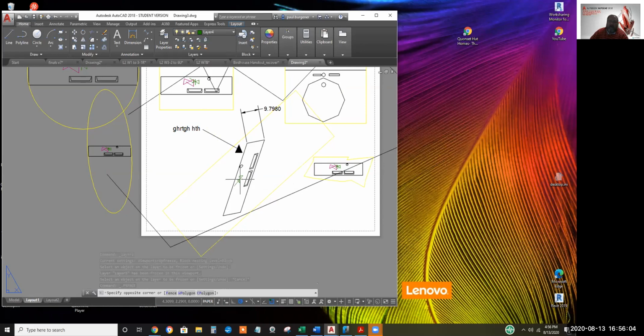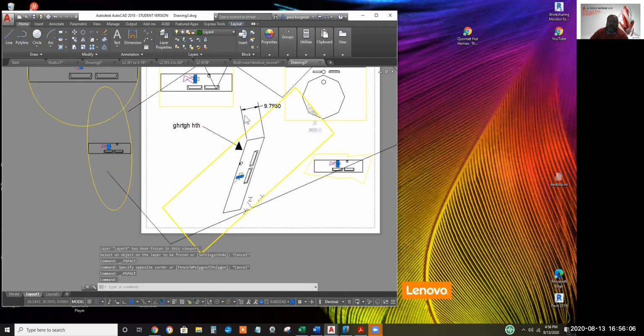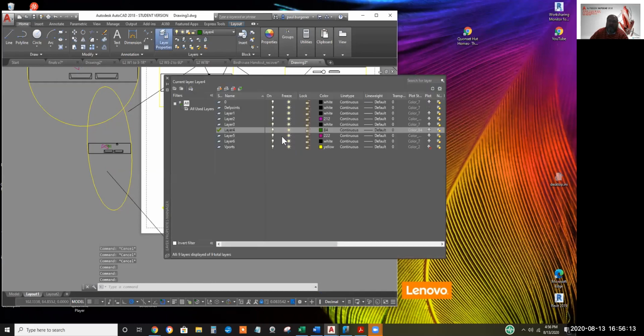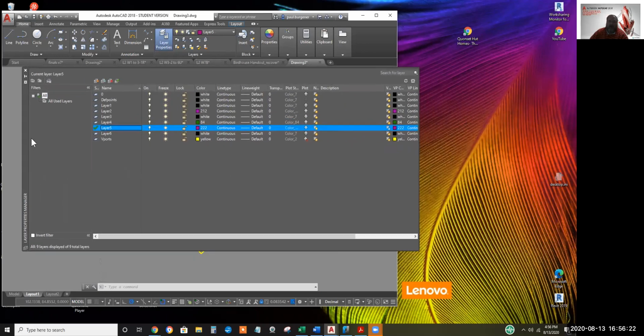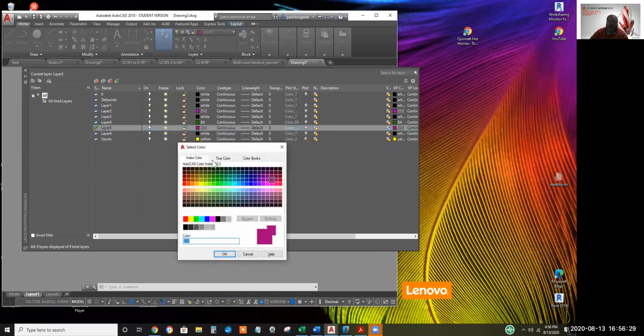In fact, there's ways, I don't think this is good practice, but while the viewport is active, you can say through this viewport, I want everything to be a different color. Kind of stepping out of the boat here. Let's see, through this viewport, I want everything on layer 5 to be this color number 80.